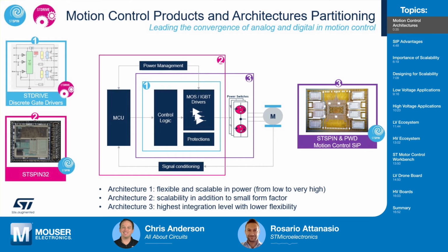In fact, if we look at this architecture, this has external power switches, and this means that if I wanted to increase the power of my application or increase the input voltage, I can eventually pick from different part numbers of FETs, IGBTs, or silicon carbide FETs, from, let's say, very low to very high voltages. So this gives a good degree of flexibility and freedom to the designer.